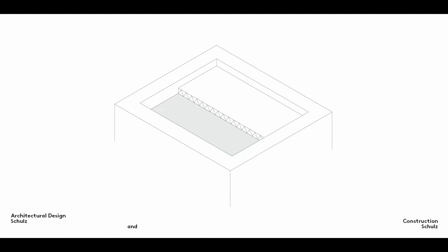A flat roof is generally located above a heated room and must therefore also be insulated against heat loss. The insulating material is usually placed on the outside of the roof slab. If standard rectangular insulation panels were used, then the flat roof would not have the necessary 2% slope. This problem is solved by the use of tapered roofing insulation. These insulating panels have a tapered section and are produced on a bespoke basis for individual roof slopes.